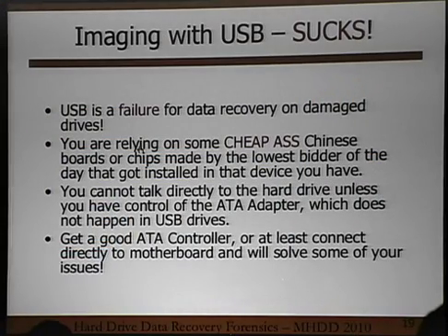USB. This is another thing I hear all the time. Everybody goes, well, I plug this into my USB adapter, I'm trying to recover data, blah, blah, blah. You guys might have forgotten, but USB sucks. When you plug this drive into USB, the ATA command set is not really in its full capacity and running and doing what it can do. It starts up a driver in any operating system. It basically starts up a driver to talk to the serial port, and it's a mass storage driver. It's a generic driver. It has no real fundamental control, so you can't do error recovery and you can't do ATA commands that are going to give you any good response.